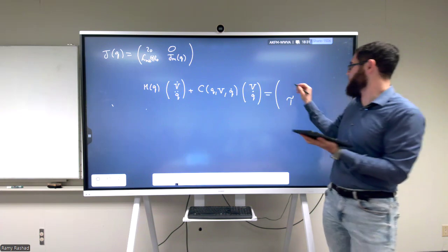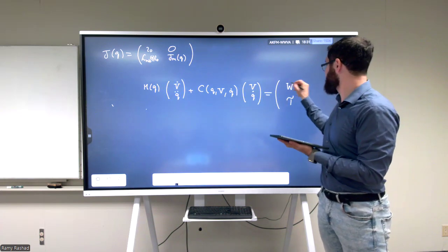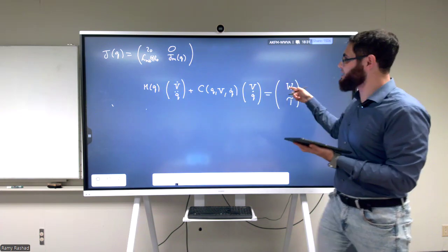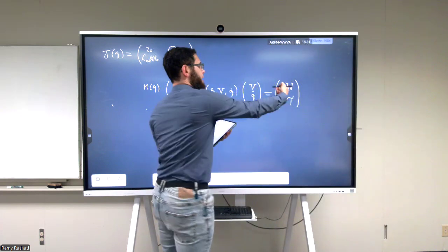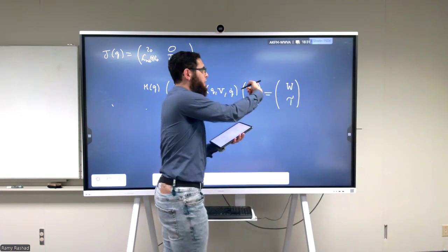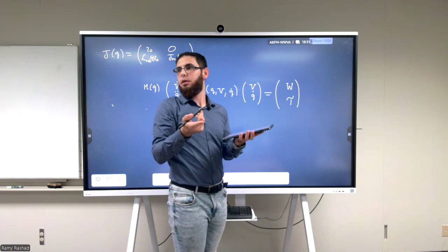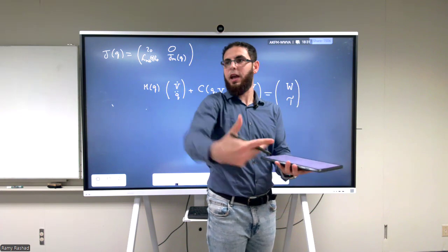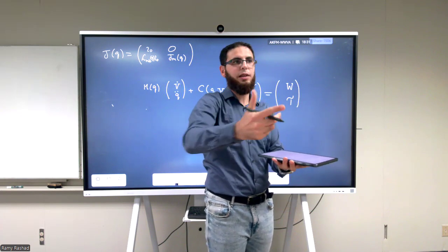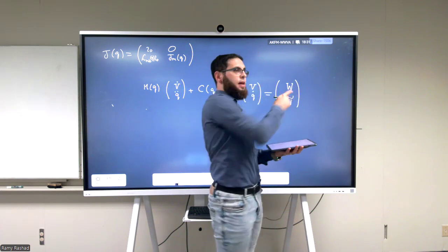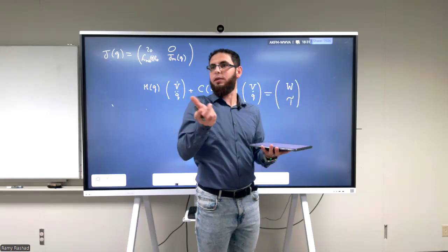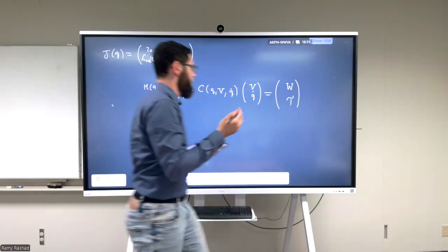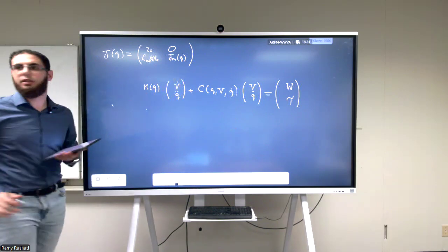If we have any forces on the base, we're going to call this a small w, the dual variable of the small v. So if v is in R^b, for example in a planar joint, if I can rotate around the z and move in the x and the y, this will be the force in the x and the y and the torque around the z that will make me move. This is just an example. But in the end, we get an equation like this.